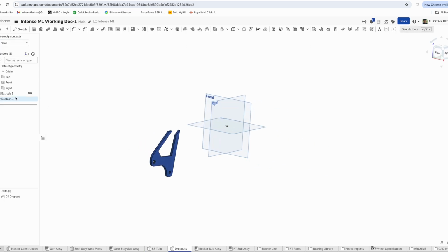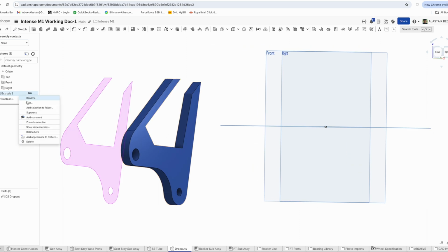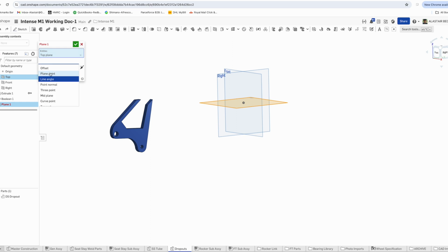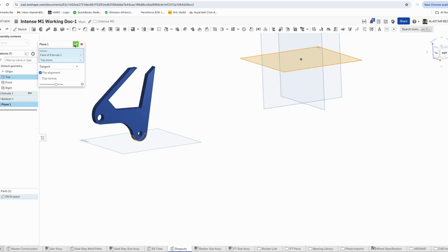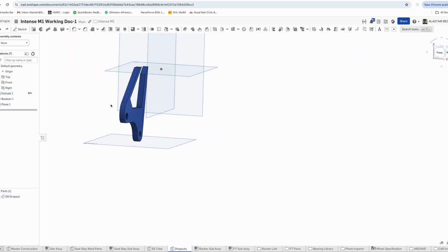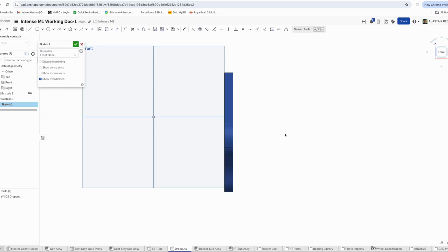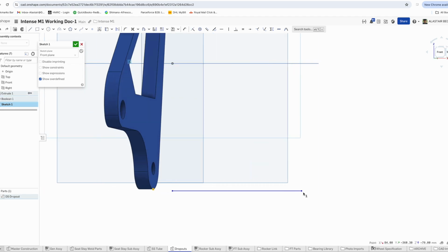So I'm just tidying up, renaming those parts, and gone back in here to increase that thickness up to 10mm, and then from that point, we know that's enough meat for our 7mm bearing plus a bit of wall in there as well. Then we'll create this surface sketch to give us more of a tapered profile as it reaches the top of the part. So that's what I'm doing here, starting on trying to create a sketch plane off the bottom. And that can be the tricky part sometimes, like where do you start your sketch on a part that's quite organic and has a lot of curves in it. So sometimes you just got to get a bit creative in how you create your planes.